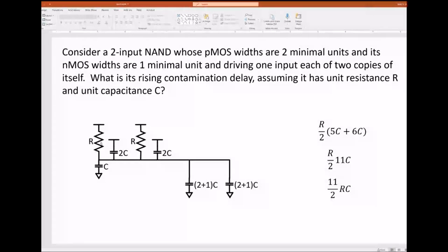Now, when you take my 611 course, I have a lecture in there about timing closure, where you're dealing with guaranteeing that if you have a circuit with memory elements in it, flip-flops, there's this idea of a setup and a hold time, and those have to be guaranteed throughout the range of delays you get, where the range of delays is going to span from the contamination delay